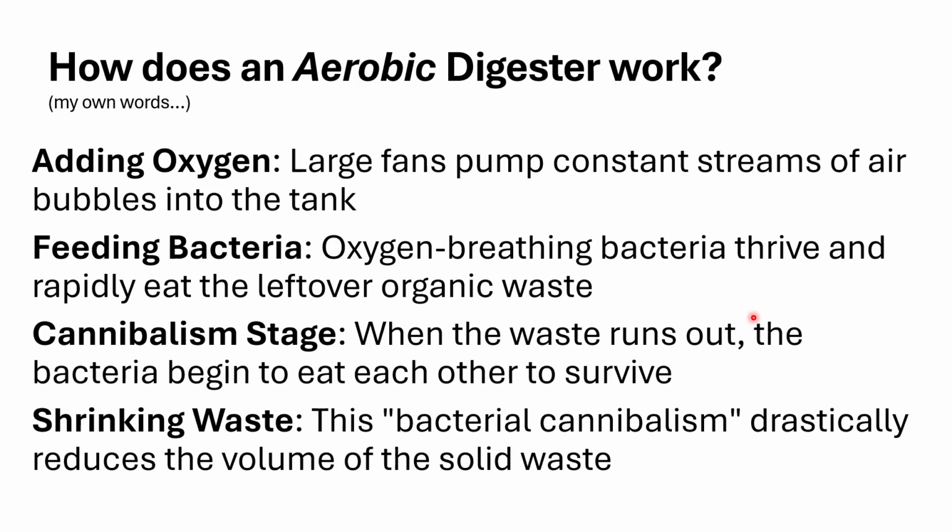So, a couple of things to think about. Keep this in mind because we're talking about activated sludge plants and it's going to become pretty important later. The BOD, I mentioned this last time, the BOD or organic material represented by that BOD, that biochemical oxygen demand, the organics coming in, that's the food. That's the food that makes these microbes work. The stuff we test for coming out of the digester, the mixed liquor suspended solids, that represents our microbes. And we have, once again, we'll get into this a little later. I know I keep promising, but we will get to it.